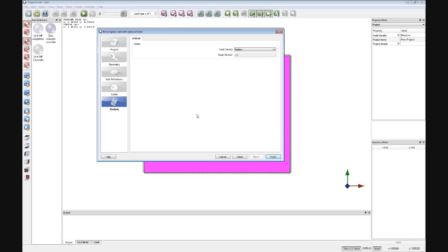So obviously if you have a very low number of nodes, then the solution won't be quite as accurate, but the time of solve will be a lot quicker. But then if you want to get within sort of 0.1% of an answer, then you put a higher number of nodes in, and you will get increasingly more accurate results.